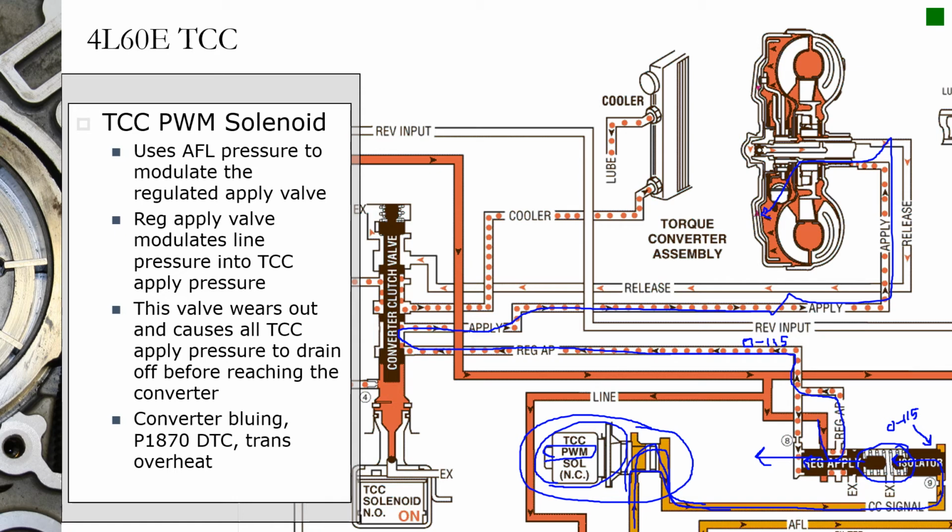When you think these converters are 10-inch converters, and you're really working across the whole surface area for the most part, so that's about, well, radius squared, 5 times 5 is 25, times pi, let's say 3, so you got 75 square inches. Even if you were operating at 100 psi, that would be 7,500 pounds of force. So that means this piston is strong enough to lift 7,500 pounds.